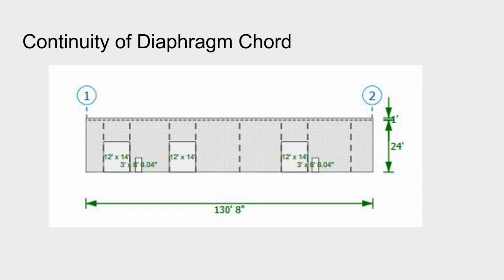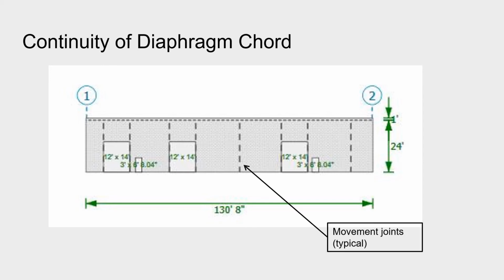Here's an elevation of a building with the wall movement joints. The elevation was created using the Direct Design software, a masonry program based upon TMS 402 and sponsored by the National Concrete Masonry Association. The joint locations are selected by the user, but the diaphragm cord reinforcement is designed by the software. The user can select whether the diaphragm is either flexible or rigid.